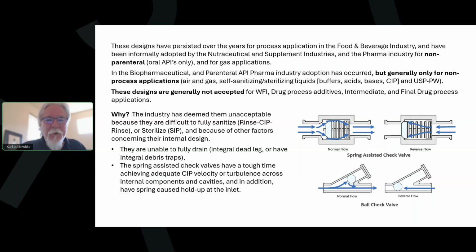because they're difficult to fully sanitize, and because of other factors regarding their internal design, namely that they are unable to fully drain. There's an internal integral dead leg. And if you look at the spring-loaded design here, most of the designs have a little cavity here that doesn't fully drain. And on the ball check, you've got this dead leg behind the ball that's tough to clean out. So that's one reason.